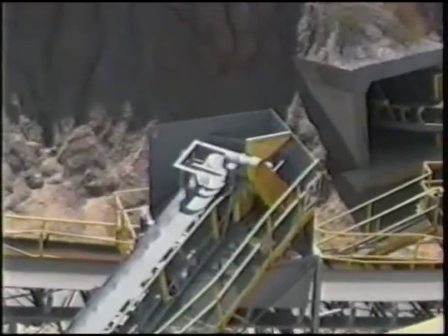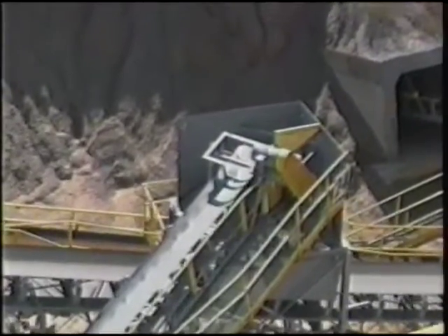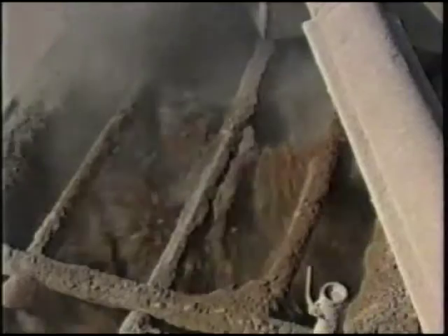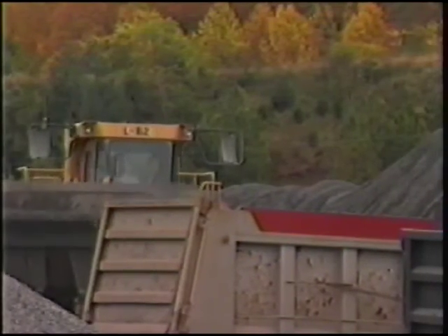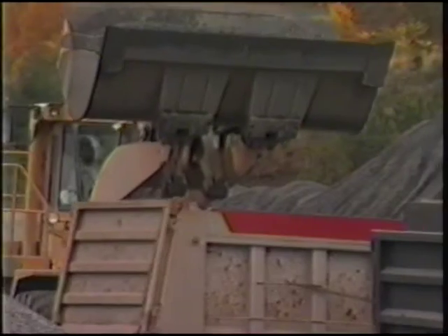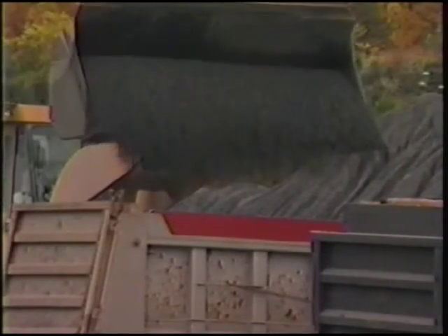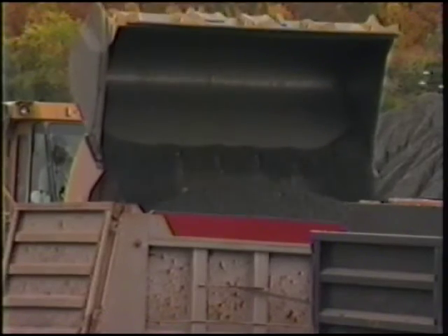There should be a separate feeder for each component aggregate size used to produce base or sub-base materials. Here, water is added and mixed to obtain optimum moisture. Pug milled material should be loaded with the same precautions as materials straight from the stockpile. Loader operators are the last to handle the aggregate. They must give particular attention to assuring that trucks are loaded properly.